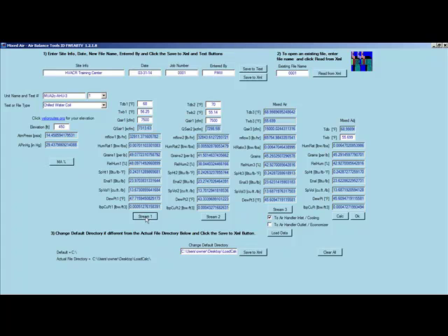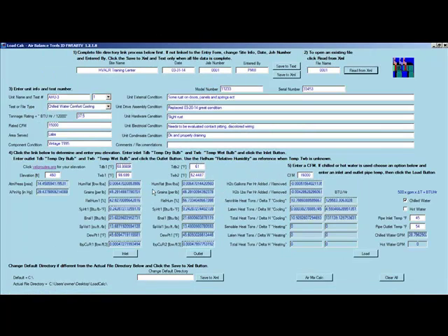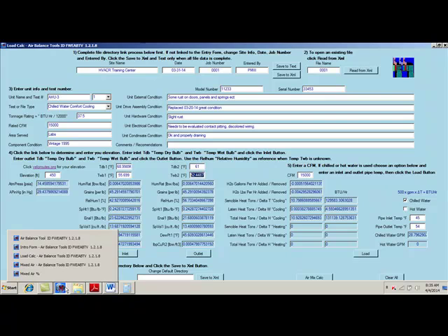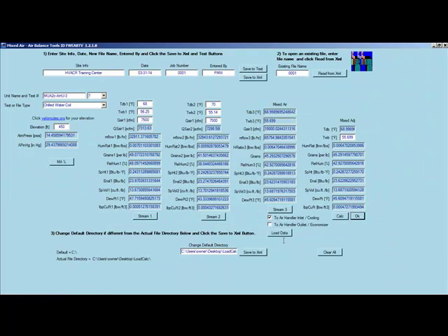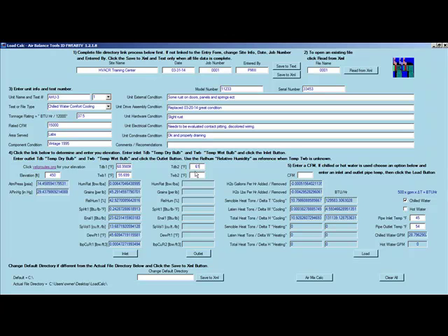We're going to calc all the buttons, and then we want to fine tune here and match our grains. So 4529, 4529, 291. Close enough. Calc, push it over. And then let's go to the load calc for air handler 3. We're going to copy that again so I don't have to try to fine tune that. We're going to push this up to the inlet of the coil. So we push the data up. We go to 61. We'll paste our data.